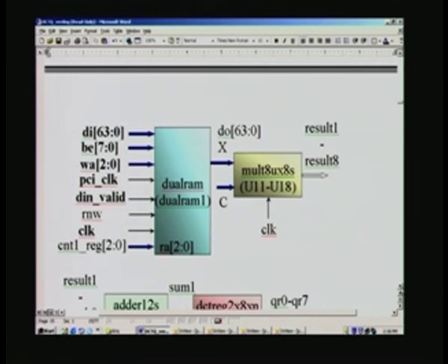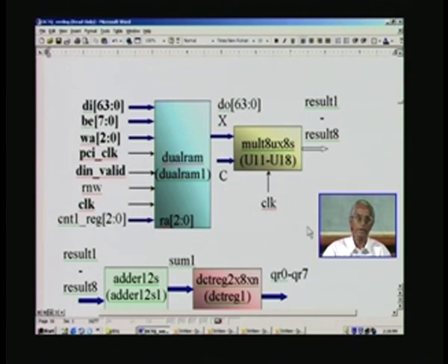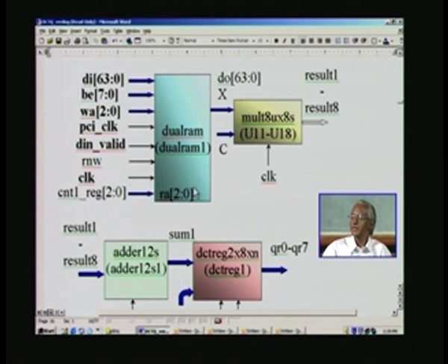So, prior to making the Verilog design, we need to put a hardware structure here, and this is what is called architecture. The architecture will have to reflect the actual hardware that we need. We have already seen the dual RAM designed earlier, and that is precisely what we are going to use here. So, I am not going to describe the dual RAM, except for the signals, merely to recollect what we had done before. All these bold notes are the pin configurations that we have seen before, a block diagram with all the IO pins there.